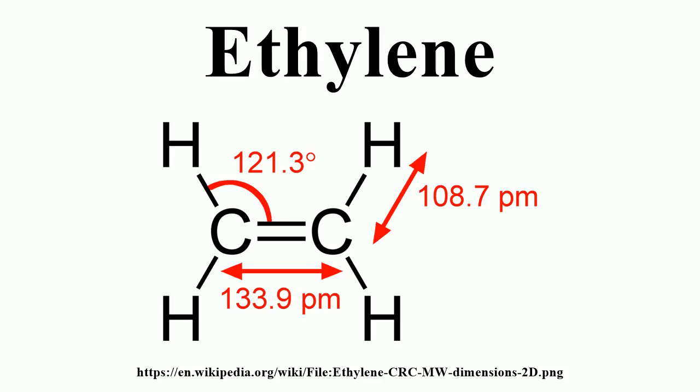Commercial ripening rooms use catalytic generators to make ethylene gas from a liquid supply of ethanol. Typically, a gassing level of 500 to 2000 ppm is used for 24 to 48 hours. Care must be taken to control carbon dioxide levels in ripening rooms when gassing, as high-temperature ripening has been seen to produce CO2 levels of 10% in 24 hours.